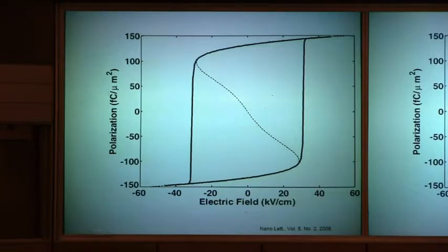And the important thing is that we need to make a negative capacitance. Therefore, polarization is important. Later I will show you how we make this kind of polarization from quantum mechanics, from first principles, and from material science. But I would say, if there's a polarization curve like this, polarization versus electric field, then there is a possibility to have this kind of negative capacitance, because dP/dE is negative.